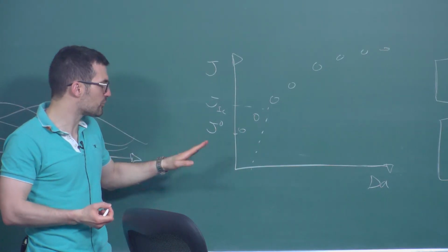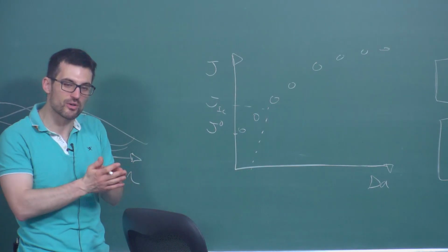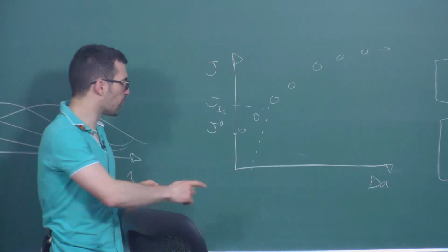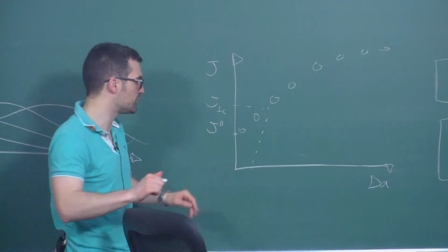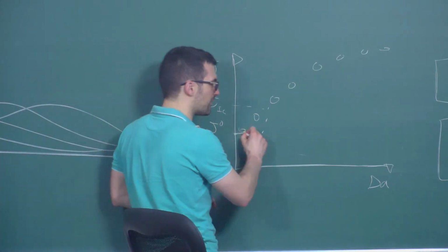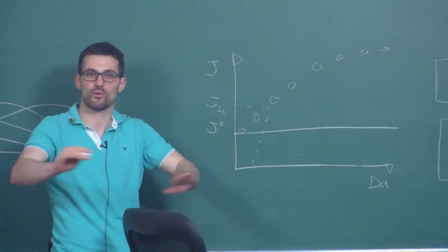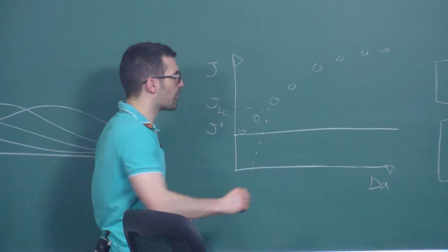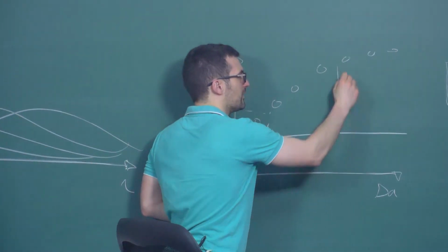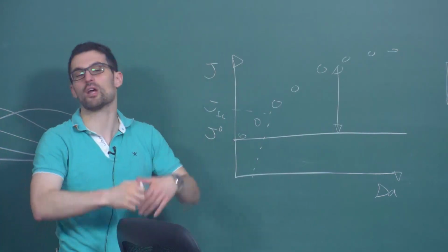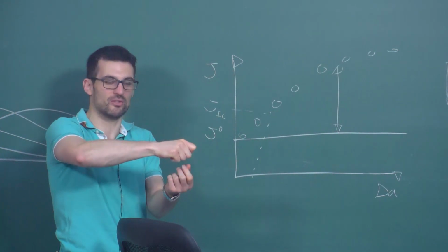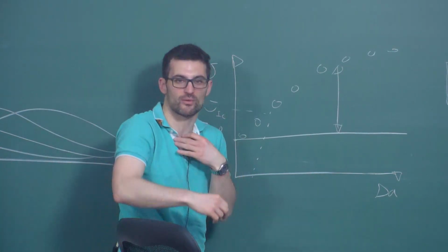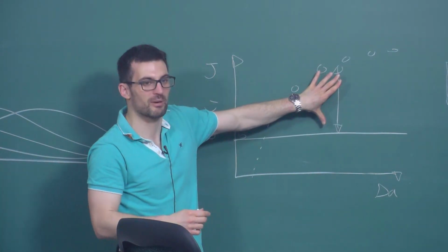the way I prefer to see this is that the fracture energy is actually a constant quantity. So if you had a purely linear elastic brittle material, what do you see? You see the cracking initiates here, and it's unstable crack growth. The crack just grows here. So what happens between here and here is plastic dissipation. Or if you have a carbon fiber reinforced polymer composite, then you will have the bridging of the fibers across the crack. So there's a toughening effect coming from plastic dissipation.